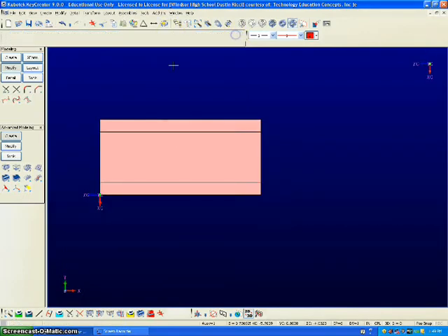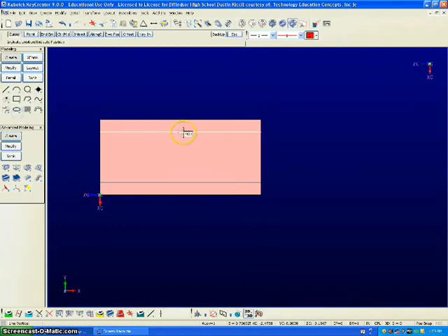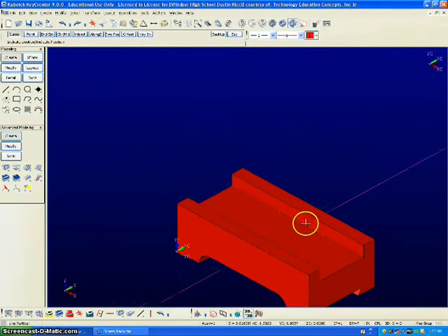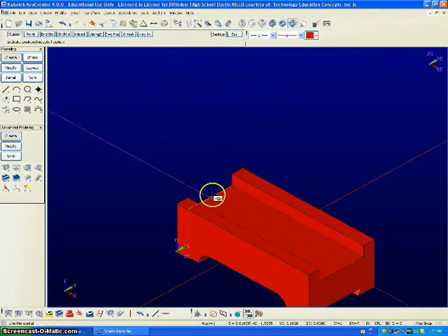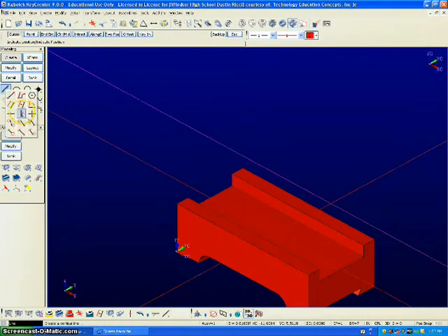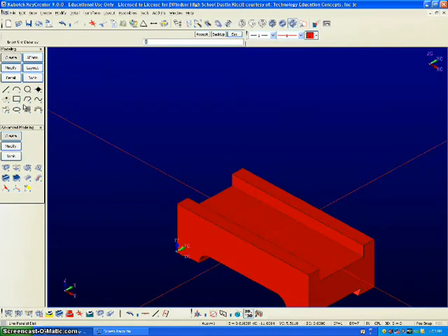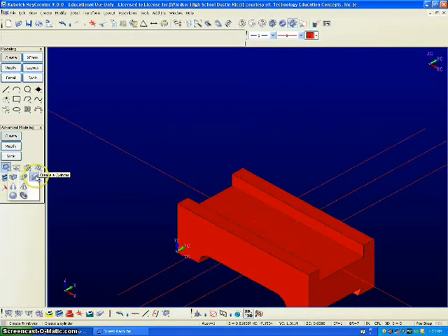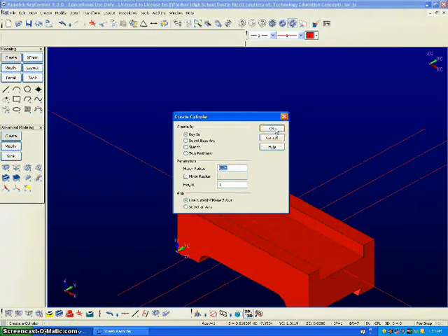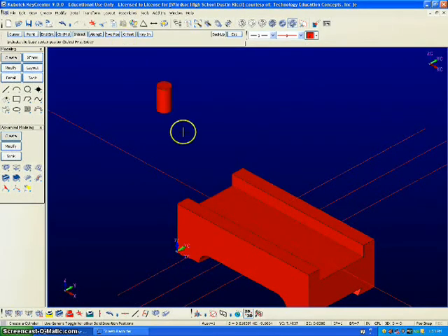And now we have to set up where our cylinders will go, so we're going to use the line tool, line vertical. So we're going to use the isometric view, and we're going to find the middle of the block and on both sides, so horizontal and vertical. This will help us create our cylinders in a couple minutes. Going to go line parallel distance 1 from this vertical line. These are where our cylinders will go. Create a cylinder, major radius 0.25, and we're just going to use the intersect tool.